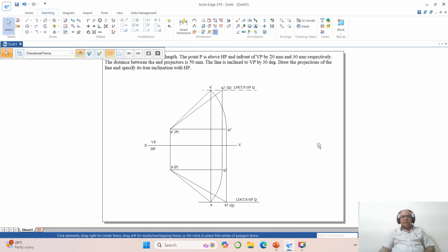Now, I need to do the thickness. You just go to this point, go to dashed outline. Now we need to write the front view. So take these two, so make it as 0.5. Then you select between these two. Take these two as 0.35. Then you select this XY line and make it as 0.13. So now all other things will be of 0.05 line.